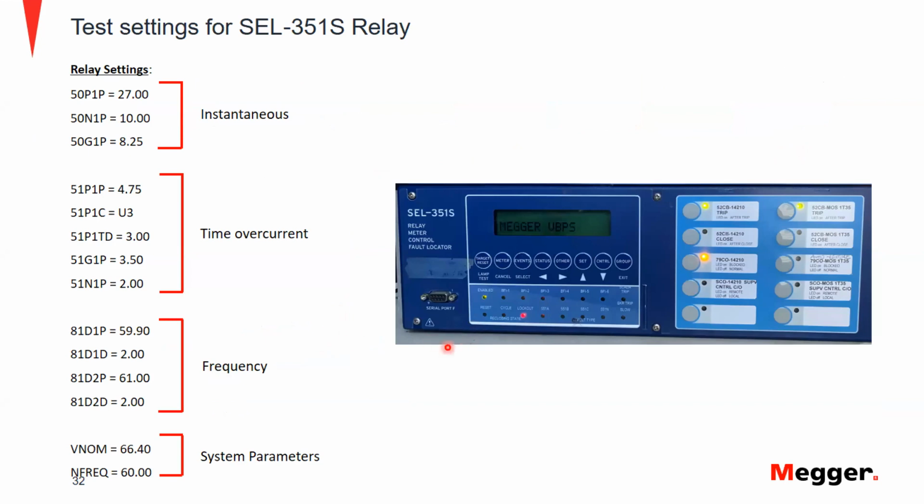So we're going to jump on this 351S, kind of give you guys a little look at my settings here. We're not going to have a huge amount of time to go through each individual test, but we are going to try to at least hit the pickups and at least hit the time current curve for the phase. And then we also want to hit some of the tests for the frequency when we do a frequency pickup along with a time delay. And then I need to give some parameters of what the system is going to be like.